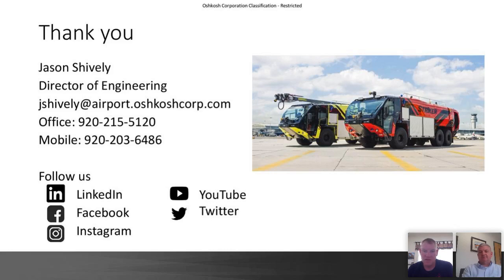All right. And how about drainage time? Does that have anything to play with it? Yeah, that's one of the key things that Keith Baggett and Mark Tunnicliffe at the FAA and I discussed as we were testing these systems out. From an operational vehicle standpoint, we're verifying that the foam percentage proportioning is properly done. So if it's a 100 GPM discharge, it's 97 GPM of water and 3 GPM of foam. It's doing the right mixing, and you get the right discharge coming out of the truck.